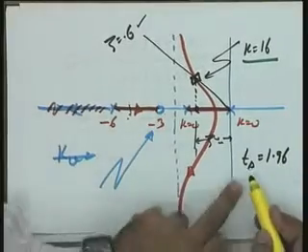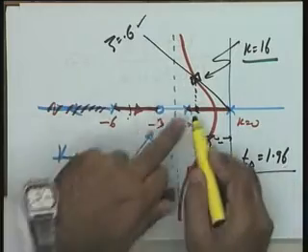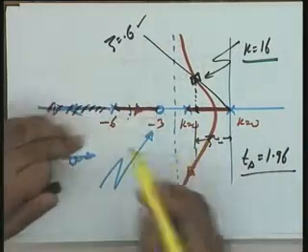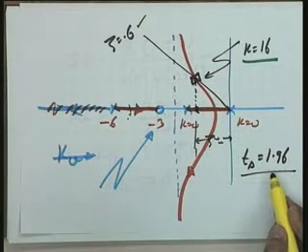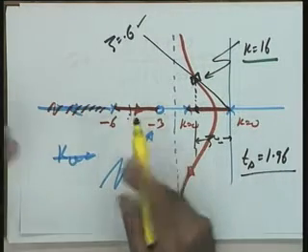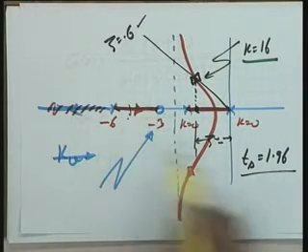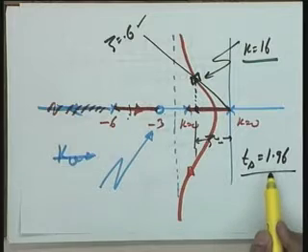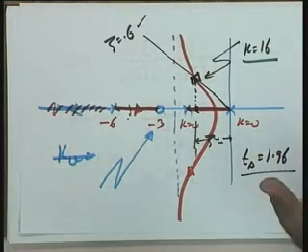So compared to Ts is equal to 1.96, which you have got without considering this third pole, if you simulate, what will happen? It will become more than 1.96, and it is still within the margin, because Ts less than 4 seconds is acceptable to you. So if the dominance condition is not satisfied, not that everything has been lost, the only point is that you have to re-examine it very carefully. This third pole is going to make the system sluggish, and you see whether the true simulation gives you settling time which is acceptable to you or not.